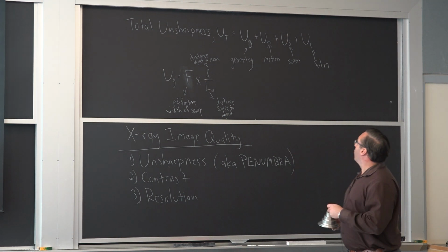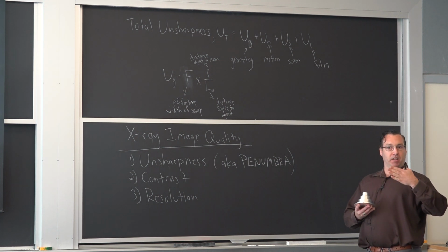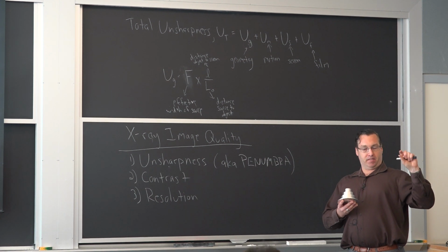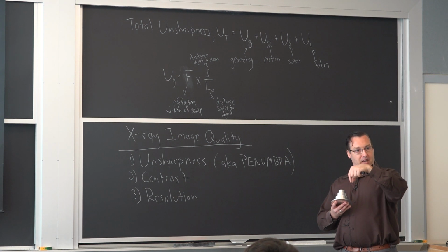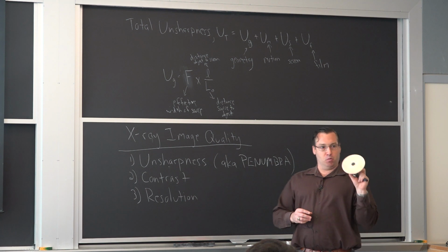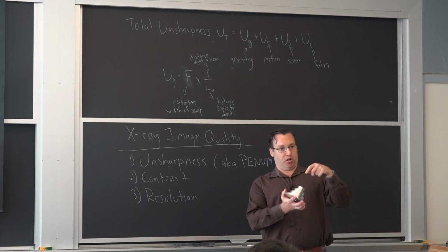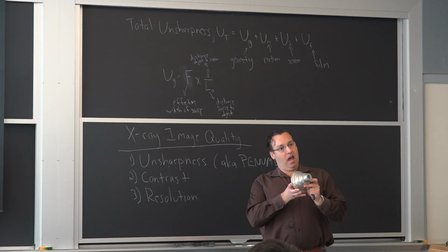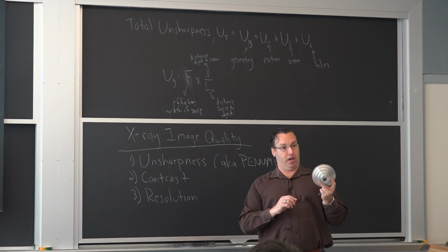So in order to minimize that type of noise, sometimes a screen is placed at the end of the source, where that tungsten filament is. If you were looking at aluminum, you can use a 1 millimeter copper screen to minimize the noise for this particular alloy. So that's a consideration that depends on the material you're looking at.